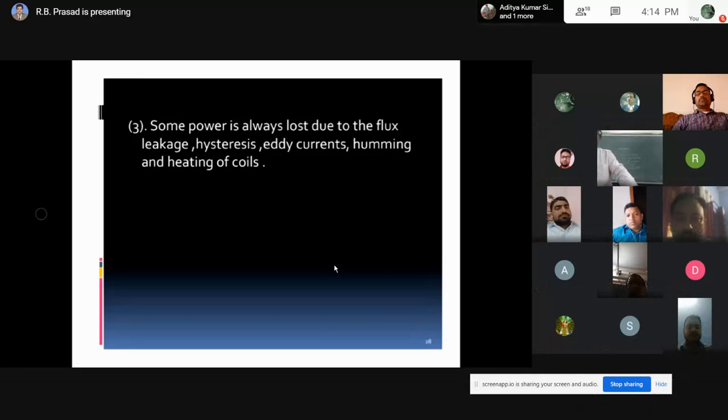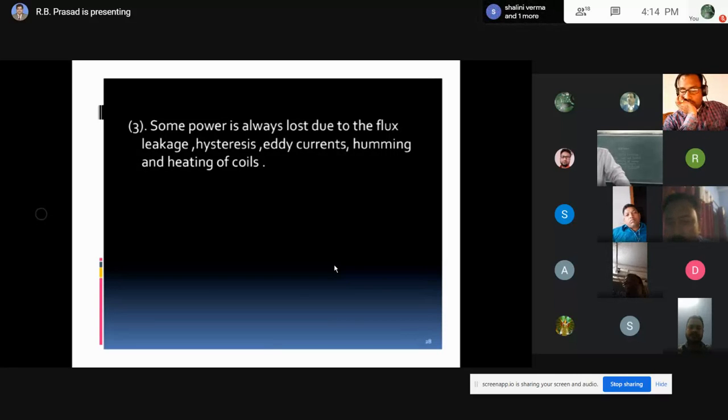Well insulated copper wire is wrapped over the core material, and due to long time and heating effect, elongation occurs. So there may be looseness of the coil, and due to this looseness, there is a vibration in the coil, and that produces the humming sound. So some part of the input energy gets lost in producing the humming sound.